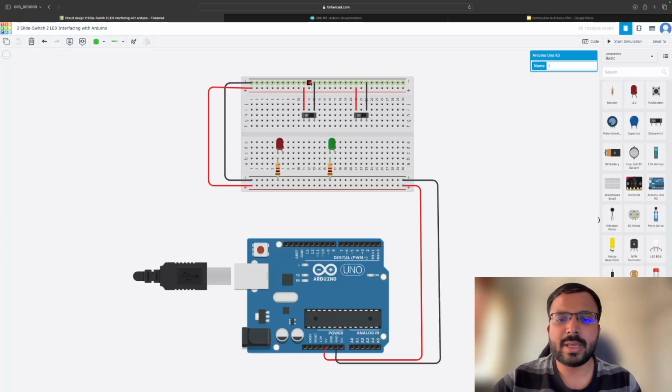And we have enough connections to make. This breadboard will provide all the outputs, and enough output pins we can connect. Ultimately in physical boards you will connect jumper wires, as we had discussed, a male and a female connector, to these, and ultimately connect to your LEDs and to your slide switches. That is how in physical boards you will connect.